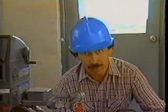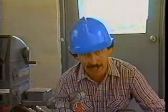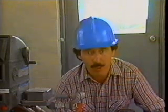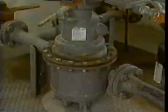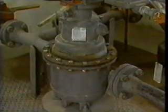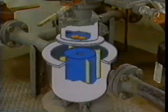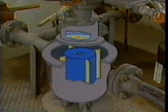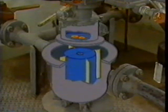There are numerous types of positive displacement meters. They include the piston, rotating disc, rotary sliding vane, oscillating piston, rotary bucket, screw and spiral vane. Commonly used meters are the rotating sliding vane and the oval gear. The positive displacement meter consists of an external housing, an internal measuring unit, and a counter-drive train. Let's look at each of these in more detail.